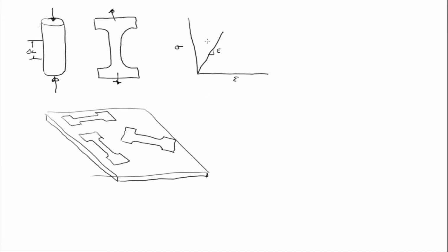constitutive tensor. But of course, steel is a fairly homogeneous material. It's fairly isotropic. So in reality, you wouldn't measure much difference in those E's for the different sample layups. And so you'd realize this is an isotropic material. But this is one hypothetical way in which you can measure the different material constants.